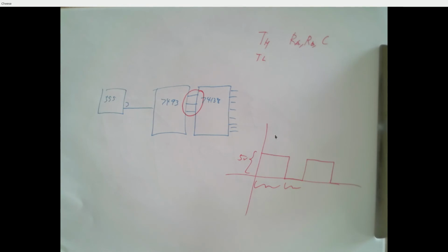So I'm going to remind you what an SR latch is in a minute. But starting Tuesday, we're going to take that SR latch and assume that this is a single unit. We're not really going to think about it as a NOR gate, where if you put a 1 in here and a 0, you get a 0 coming out. We're going to think of it as an SR latch, and try to understand what that means. The reason being, we're going to take that SR latch, add some other circuitry outside it, and create something called a D latch.